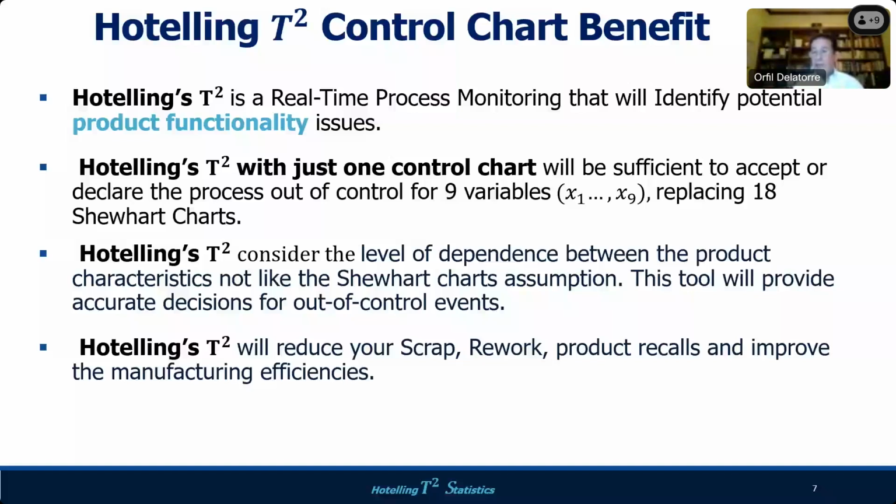But what happened? They used to have SPC control charts for both, for the shafts and for the bushings. But nothing was identified as an issue because both were in compliance with the specification. So that's why those shafts and bushings were not rejected in process. Because again, the SPC is not considering the covariance. I hope I explained the issue with this example.